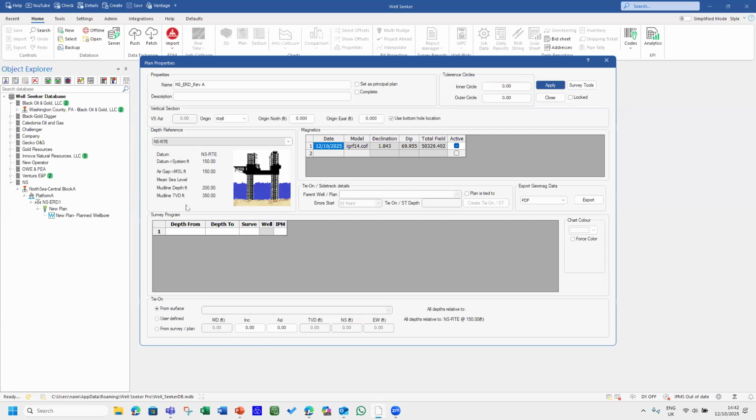All it does is drill a vertical well to X number of feet, let's say 1,000 feet or whatever, and then leave. They are very low cost rigs. For a well, they just drill the top hole and leave. And then the next rig will come and drill the rest of it, the expensive one. So you save a whole lot of money that way. This is very, very common. It's not rocket science. Okay, so moving on.